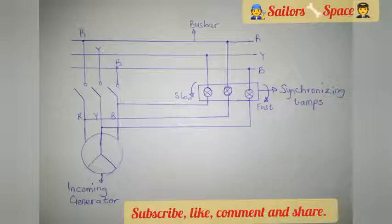You should also note that when the light flickers, it shows that the phase sequence are not the same. But when the lights are stable, the red light is dark, and the two other lights are equally bright. That shows that they're in phase and the voltage are the same, and you can close your circuit breaker for